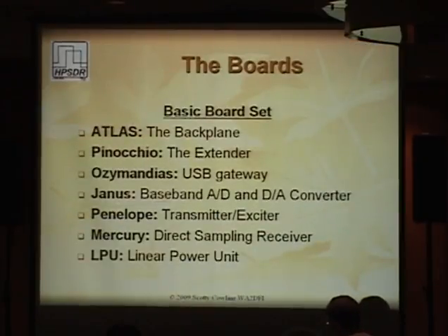Okay, so now we get into the nitty-gritty of the board set. Again, I took out most of the basic stuff because I want to focus on the new things, but I will review this really quickly for you. The Atlas is the backplane. It's a 6-slot, uses an ATX power supply. So you can either use a mini box type supply, or we actually have a supply that will plug into the 20-pin ATX connector. Or if you've got an old PC supply laying around, good luck with the noise that you're going to get out of it, but it'll still work.